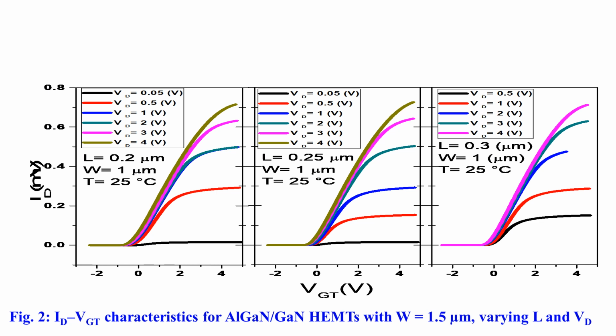Once the extrapolation method is selected, the drain current by gate voltage curves are normalized using VGT, that is, the gate voltage minus the threshold voltage in absolute value, enabling a direct comparison between devices with different geometries. The result of this standardization is shown in Figures 2 and 3.